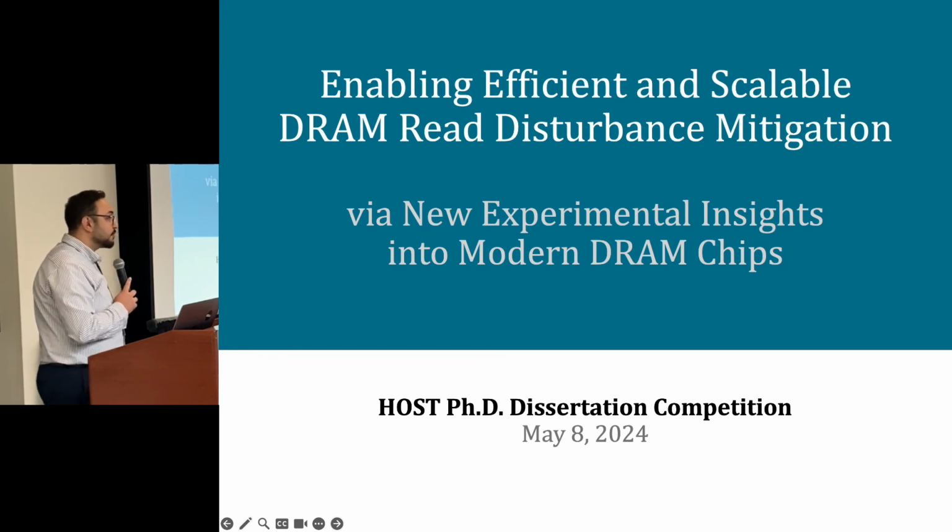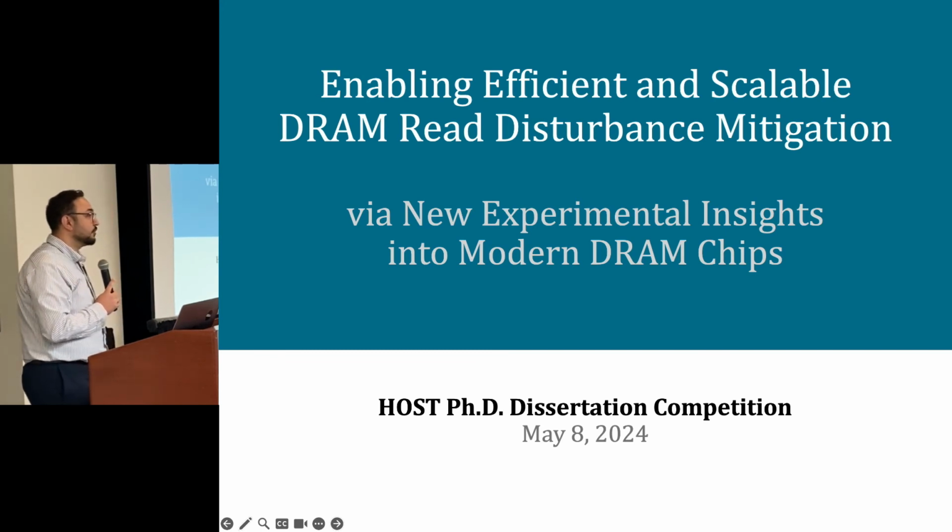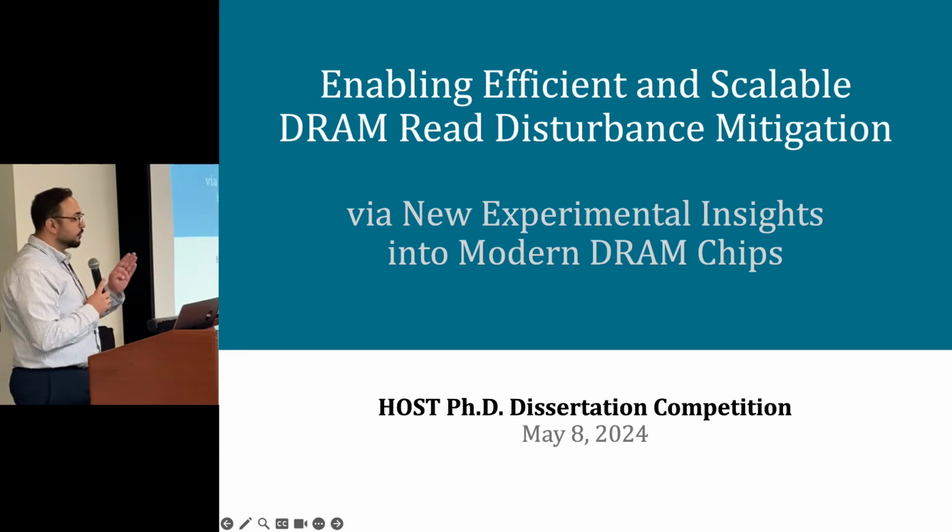Yes, it's an ongoing research problem actually. You really need to rigorously test whatever DRAM chip you have at the moment. There is a large variation caused by random manufacturing process variation. Then we also observe some impact of design-induced variations as well. For example, you look at some columns that are vulnerable to RowHammer, and you compare them across different chips in the same module, and you observe that the same column is vulnerable across all chips.